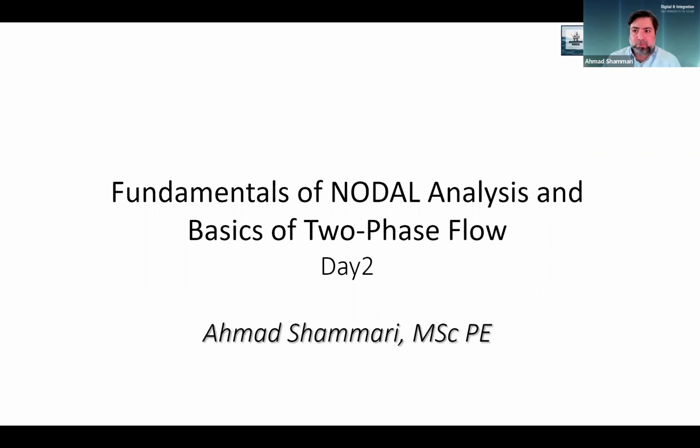If you have attended our first session, we spoke about the basics of nodal analysis and what the applications of nodal analysis are, how we can use nodal analysis to determine several well production conditions by evaluating the effect of fluid phase ratio, for example, changing of water cut, changing of GOR, which of course will change the density.